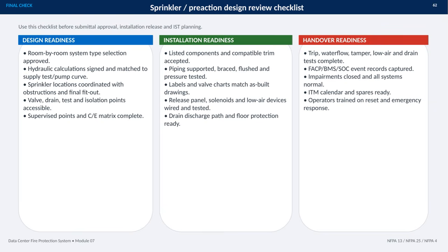Finally, handover requires completed trip, water flow, tamper, low air, and drain tests, captured event records, closed impairments, ready maintenance resources, and trained operators. These checks should align with NFPA 13, NFPA 25, and NFPA 4.